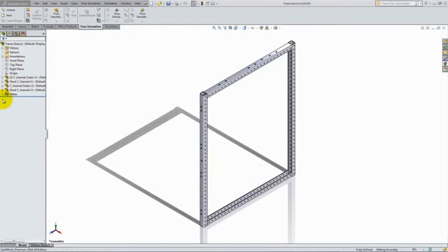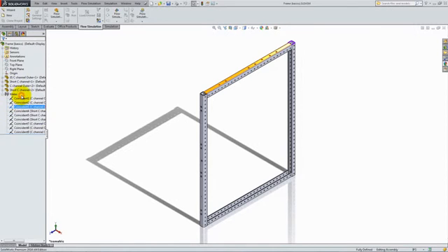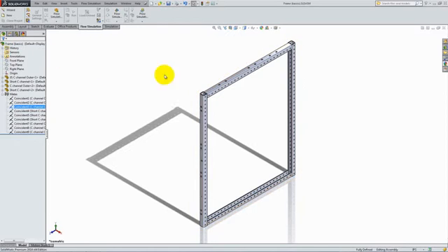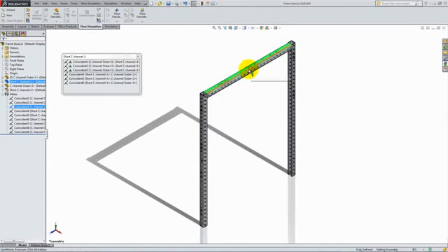When working with assemblies, it is the most effective to look at the mates between components. You can do this from the Feature Manager by expanding the Mates folder, clicking on each of them, and right-click Edit Feature to view more details. You can also right-click on a particular part in the Graphics area or in the Feature Manager and click View Mates to view only the mates applied to that part.